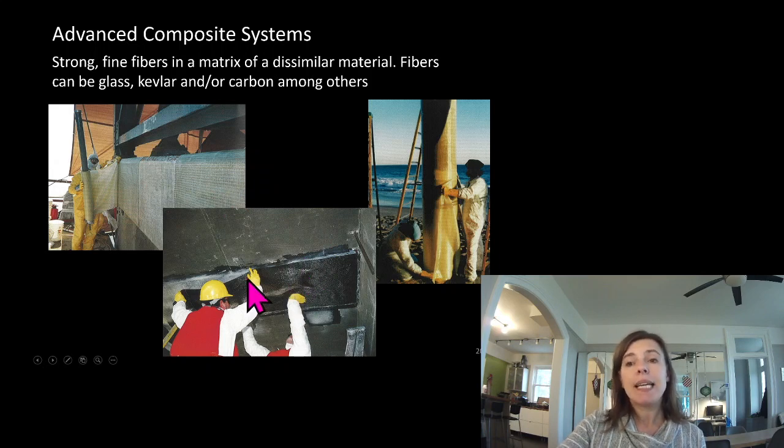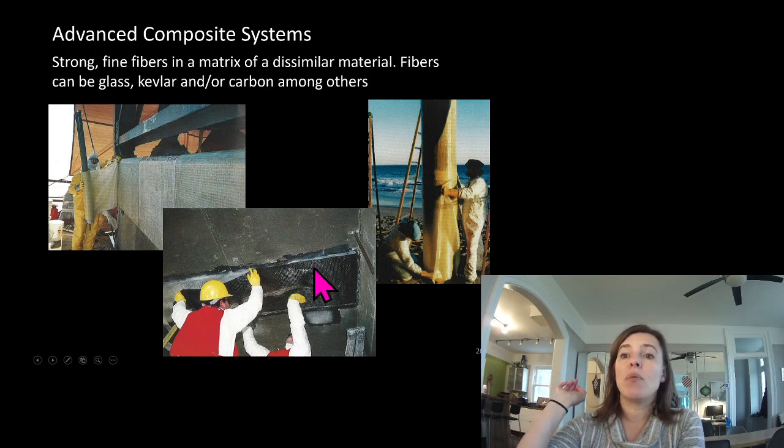Well, one, it's really expensive. Two, it has no compressive strength whatsoever. It's because we're laminating it onto the concrete that it has strength. And so why wouldn't you just do it on concrete right away? Like I said, it's really expensive. So where we use this is often in remediation work.